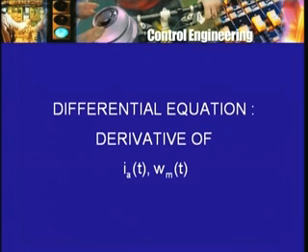Back EMF is proportional to armature current is simply arithmetic, but the electrical circuit equation already involves a derivative of the armature current, and so it's more complicated than a simple arithmetical equation. As you can therefore expect, a little bit of calculus, or derivatives, is coming in here.